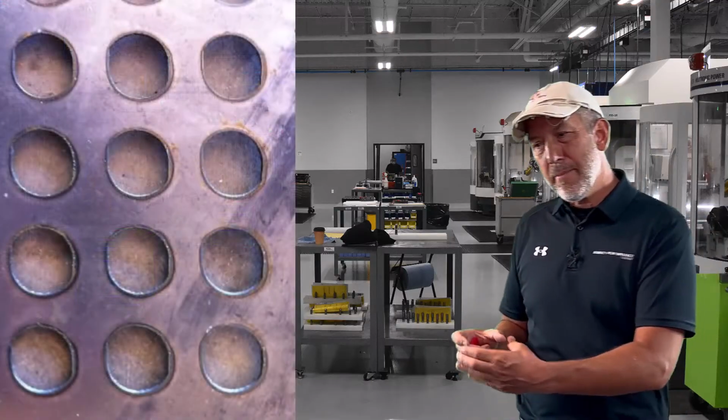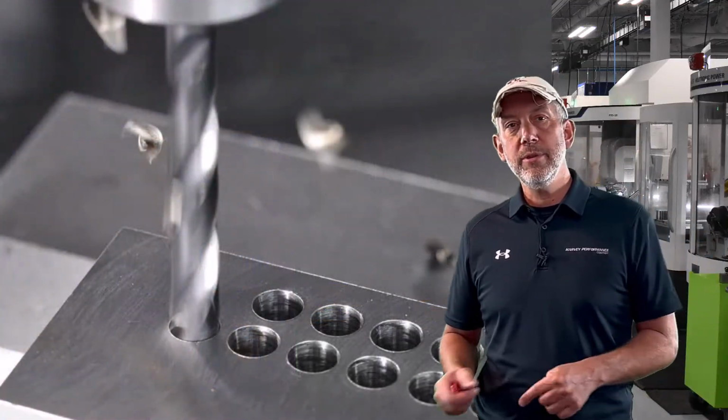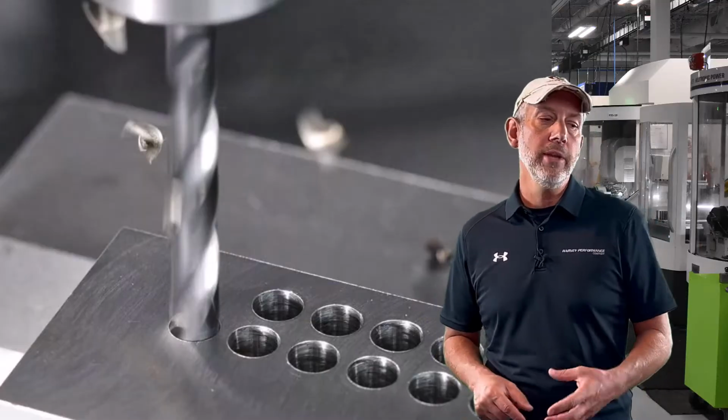High-speed steel and cobalt, if you put a lot of pressure to it, because of the point, it might want to walk a little bit. It might not be as round as you think it might want to be, depending on what kind of high-speed steel or cobalt. Therefore, you can get away with using high-speed steel or cobalt in a hole where the quality might be a little bit less.